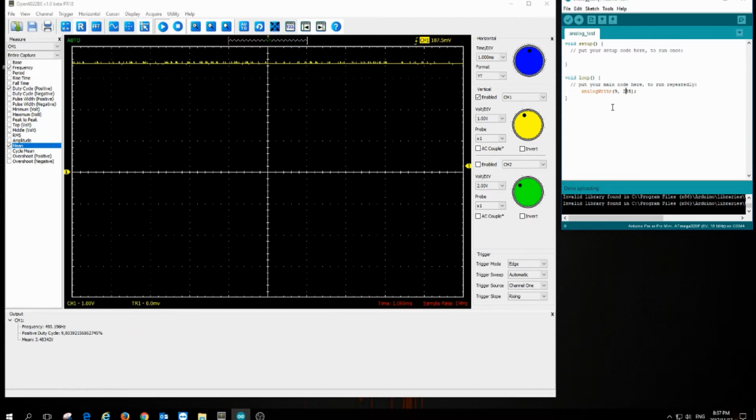So we're going to run it at 252.5. Let's see if the scope will pick it up. Theoretically, everything should work pretty well. There it is. So you see we're at 99% duty cycle, which can be seen down here, and we're almost at peak DC voltage. You can see we're on and only off for a fraction of time and then back on again. So that kind of gives you an understanding of how pulse width works.